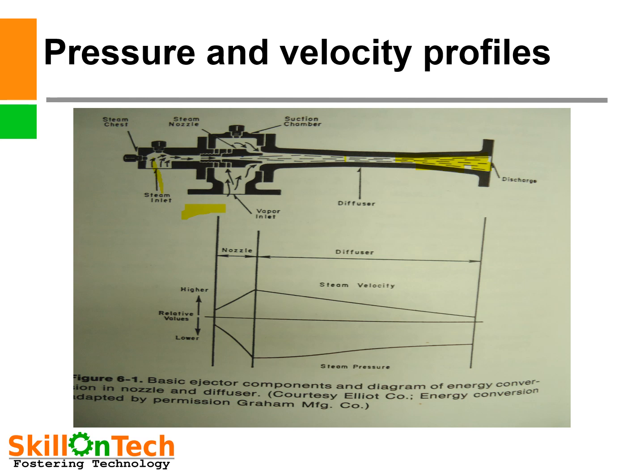When area decreases, kinetic energy will increase. So this is a throat. Here also in the nozzle, the velocity just after the exit of the nozzle will be very high and pressure will be less. Similarly it is shown here in this picture, the velocity profile of the steam ejector.